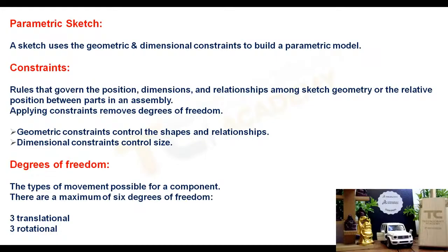For example, let's say I have a rectangle, only a rectangle. Can I say that is a parametric sketch? No. I should have geometrical constraints like that: at the corners, we should have perpendicular, and for the top and bottom edges, we should have parallelism. So then that can be a rectangle.